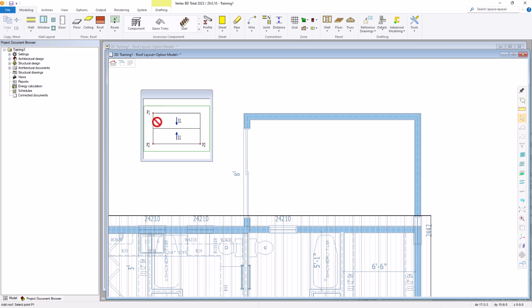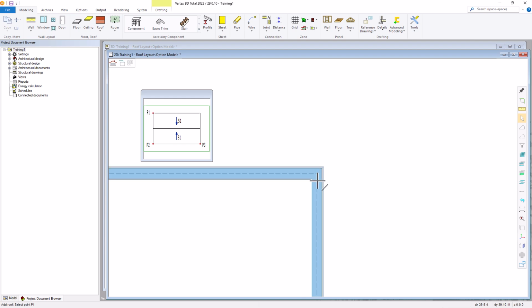And also these points that you're selecting are to be on the eave or overhang, not on the wall where our overhangs are. So let's just assume this is a 12-inch overhang that we're going to set. So we'll go in and let's start with our point 1, which will be out here.